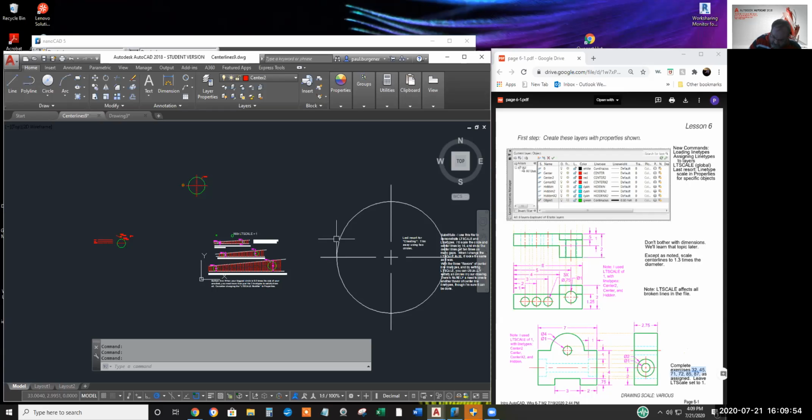Earlier I was listing the factors that determine how many repetitions a line has. Remember: the line type of the layer, the length of the line, the global LT scale over the entire drawing that affects all broken lines, and the last thing is the object's properties, whatever you want to call that number in the properties dialog box for selected objects.